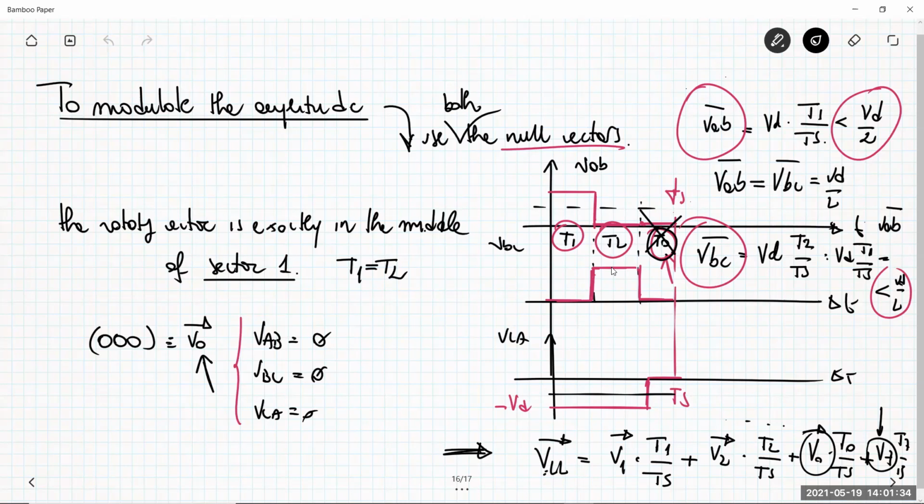As a matter of fact, you can have even a better spectrum with respect to that of a sine wave, in the sense that exploiting some specific symmetries, that I will mention later in this explanation, maybe tomorrow, you will be able to reduce the amount of high order harmonics with respect to the linear pulse width modulation.